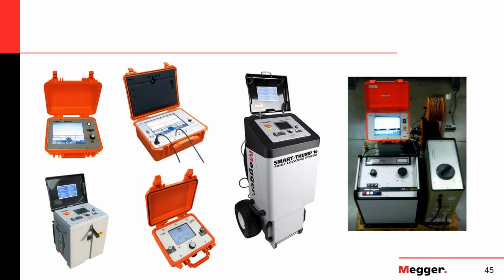So what has Megger to offer? Just a few things. On the left, you can see some radars, TDRs. Then we have on the left lower corner the Easy Thump. It's a small thumper, 12 kV system. In the middle, you see one of the bigger units, a 16 kV dual stage thumper, 1500 joules.